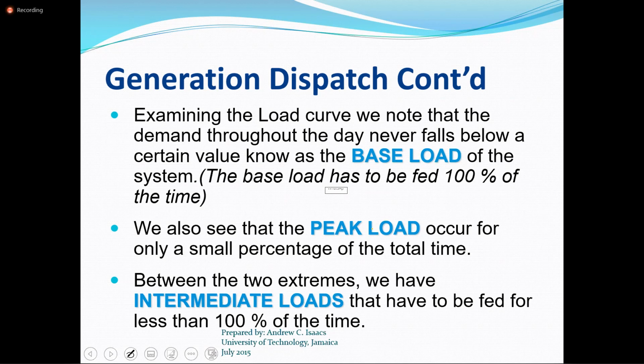As a matter of fact, you remember in Networks 1, when we were doing nodal analysis, that reference node, not bus, that we always talk about, would be like a slack bus. Because all the node voltages, all the voltages within the system, all the bus voltages within the system are given relative to the slack.